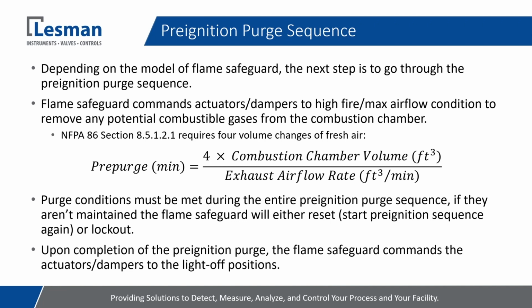FireEye does this a little differently on some of their flame safeguards. They have configuration jumpers, which give you a little bit more flexibility in your purge timing. So you could, depending upon the model, set that for exactly 45 seconds. I think it's either in like 5 or 10-second intervals for their flame safeguards. And then some of the newer products like the Honeywell Slate system, you can put in to the exact second what your pre-purge time is.